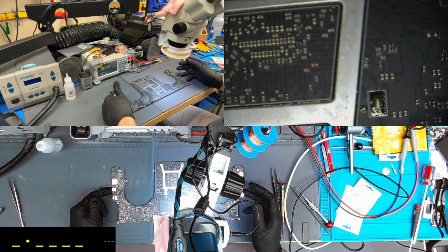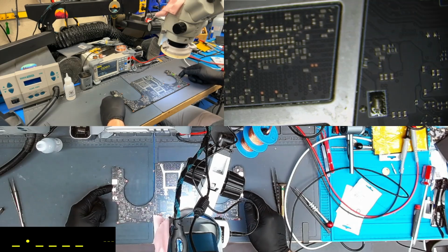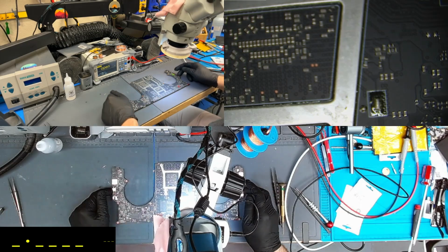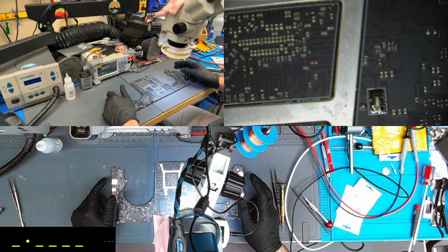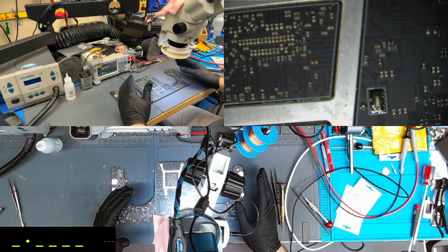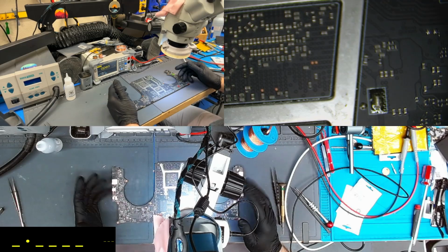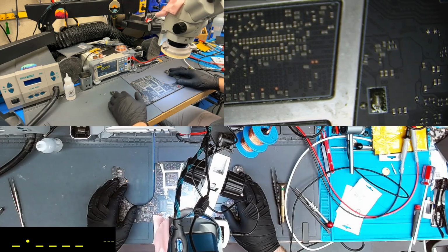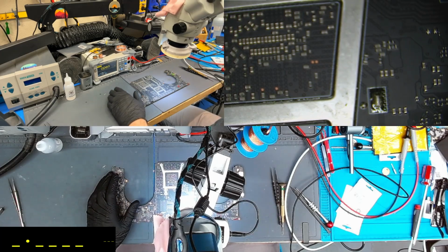But this has USB-C ports. So what I can do is plug in a USB-C amp meter and see what it's doing. Basically, we get 20 volts on the USB-C, low current. A lot of these Windows machines, you need to press the power button for them to actually go into further power states. They won't automatically turn on like a MacBook. In any case, you press the power button, nothing happens. This sort of 20 volts, low current generically tells us there's some kind of problem on a very early stage power rail.